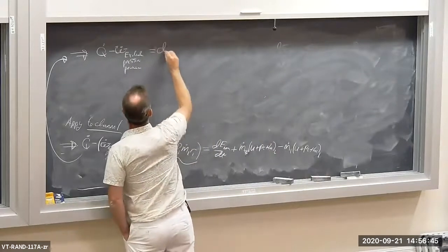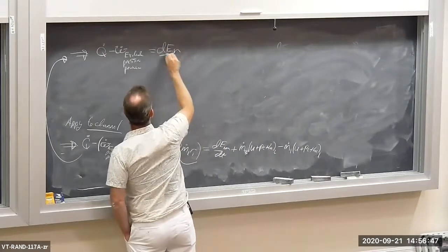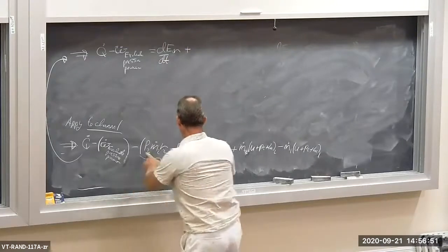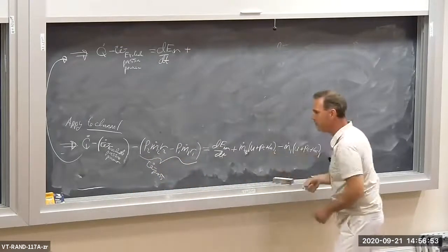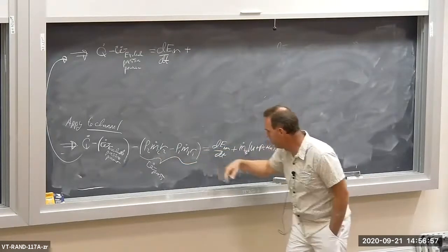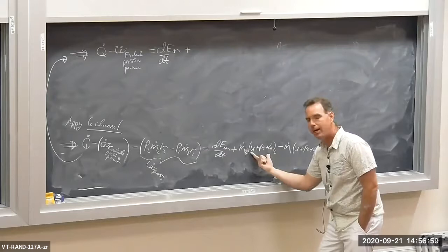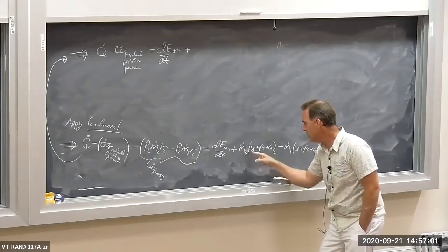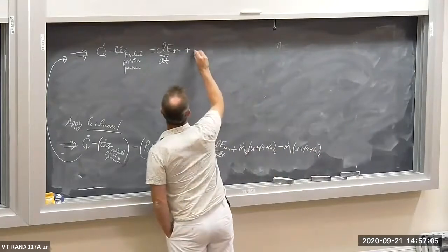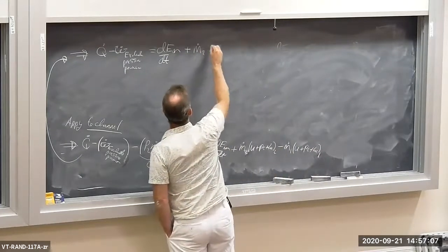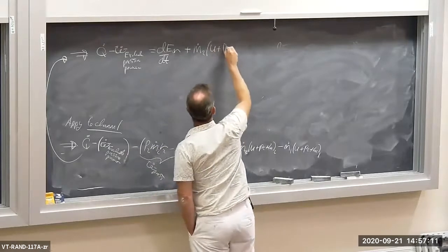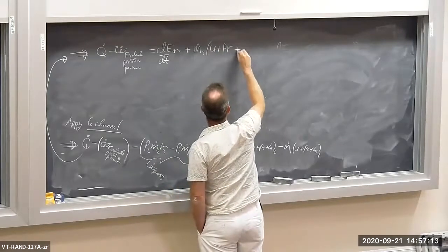And then I got the time rate of change of energy within my channel. And then I'm going to take this term and put it over on the right, and I'll have an m dot P2 V2, which I can combine in this term, m dot U plus PE plus KE. So m dot 2, U plus pressure times specific volume.